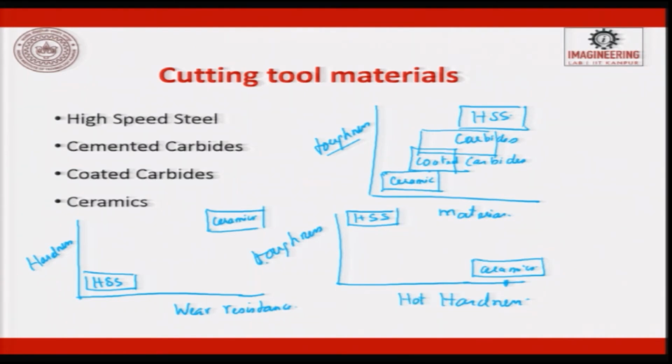Depending upon the single material property, you will see the presence of the tool material. So, tool material plays a very important role, and deciding the tool material for our requirement plays another important role. So, you will have high speed steel, you will have cemented carbide, you will have coated carbides, you will have ceramics. Today you have cermets also, where ceramic plus metal is there, and again in ceramics you will have coated ceramics, and finally you will have diamond, the hardest material which is there in mankind. So, diamond is also used as a cutting tool material. In CNC we use diamond tools also for machining.